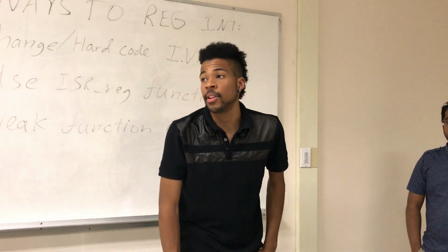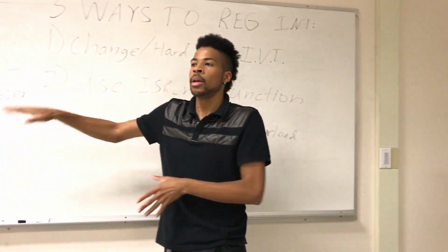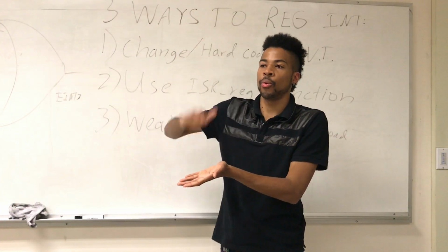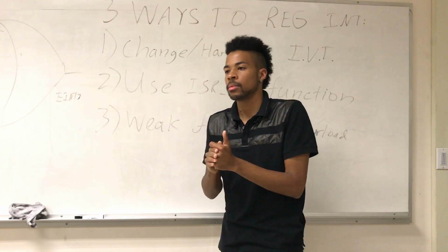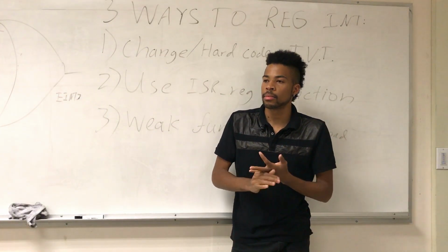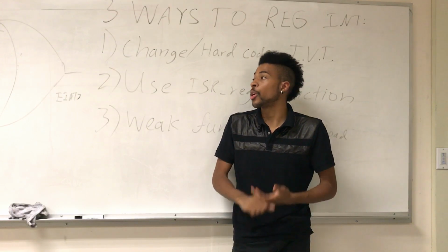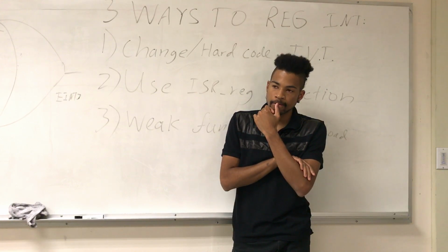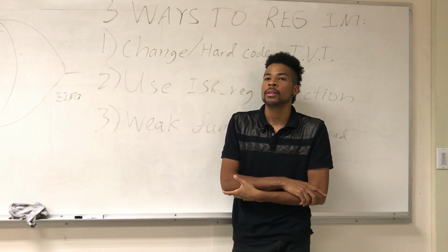I'll send out a message to give you the right source. I remember seeing this before, but I can't find it right now. It explains the correlation between EINT3 and all the other GPIOs, and the statement that says all GPIOs are registered under this. So I'm thinking that the pin they designate in there is probably a dedicated EINT3 pin. Yes. But it can also be triggered by other GPIO pins. That one can't be used by anything else but EINT3. Sure. Okay.